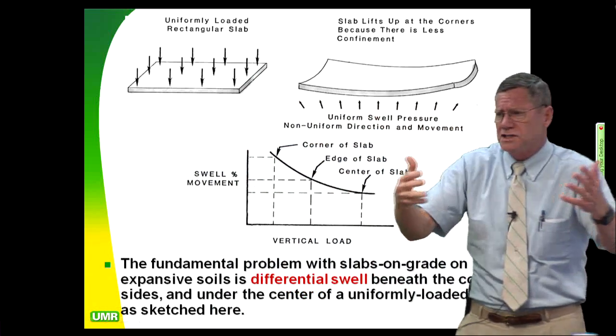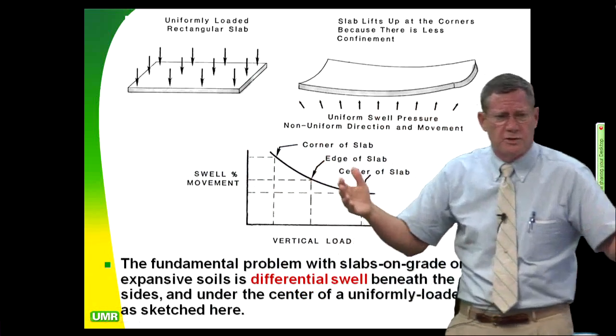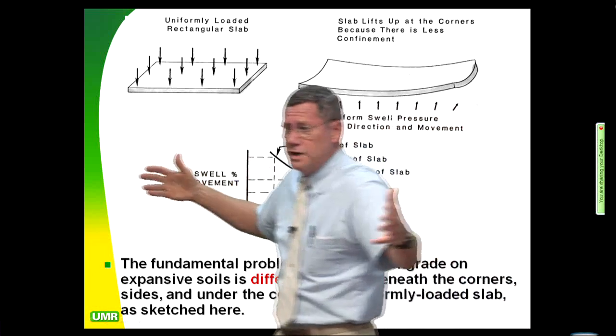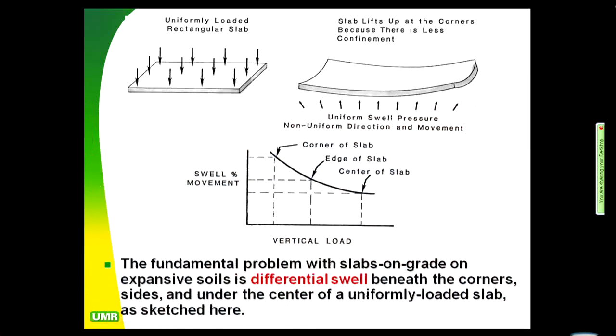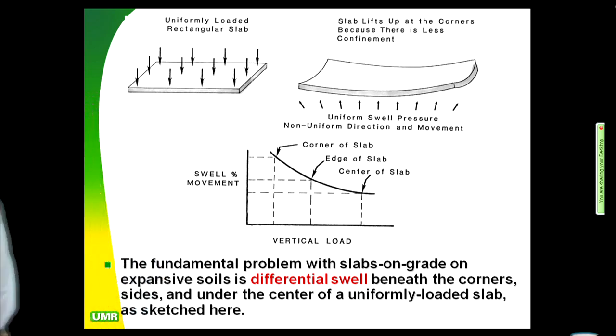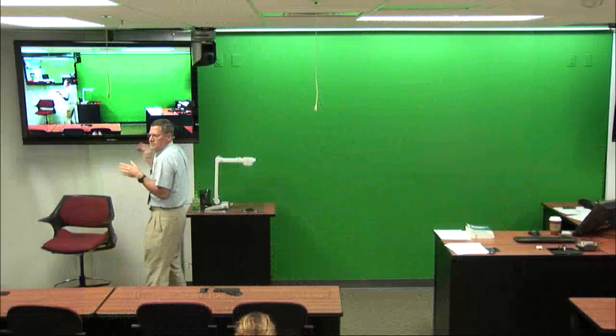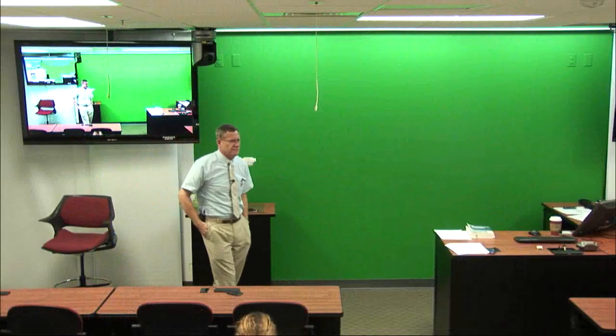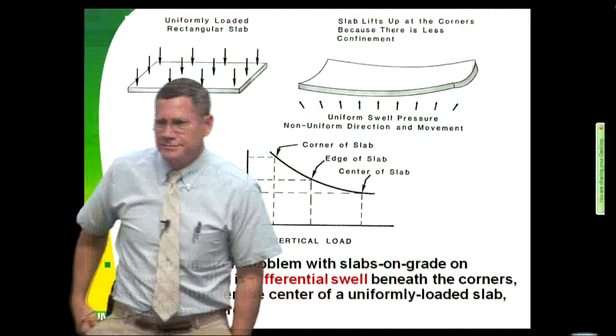If I took all of us together, and I used to do this before political correctness came in on us, but I got all the boys and girls and pushed us all over here in the corner together and got real close. And then I asked you for all your respective weights, which the girls don't usually give, but anyway. And we added up all of the weights, and we divided by the triangular area here that we're all squished into. We get about 35 PSF, 35 pounds per square foot. That's not a hard thing to design for.